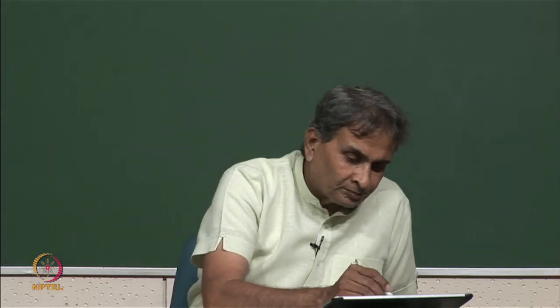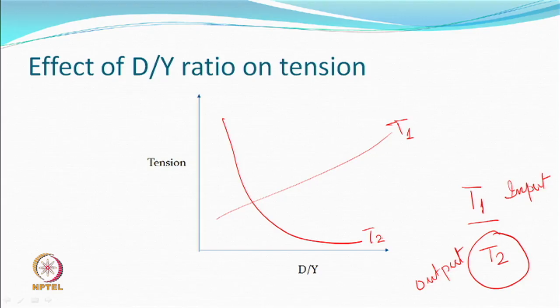The yarn is not just passing over something called a disc, it is also twisting and also simultaneously untwisting. At one area it twists, in the other area it untwists. If twisting means increase in tension, untwisting should mean the opposite of that, right. So, this is surprising, but not so surprising. That means the T2 actually can follow a curve like this.